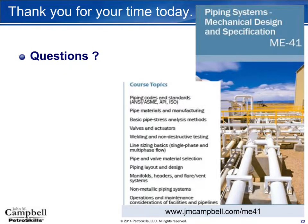Typically speaking, we utilize a 12.5% mill tolerance on carbon steel piping, unless it's API 5L, where we jump to a 10% mill tolerance. And that manufacturing tolerance tends to vary. Off the top of my head, I seem to remember at 20-inch, the manufacturing tolerance changes from 12.5% down to 10%. So just be cognizant that they vary based on manufacturing method as well as the actual nominal size.